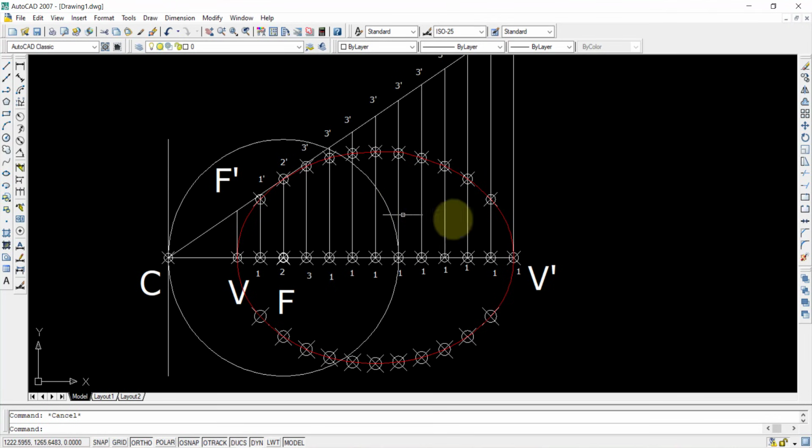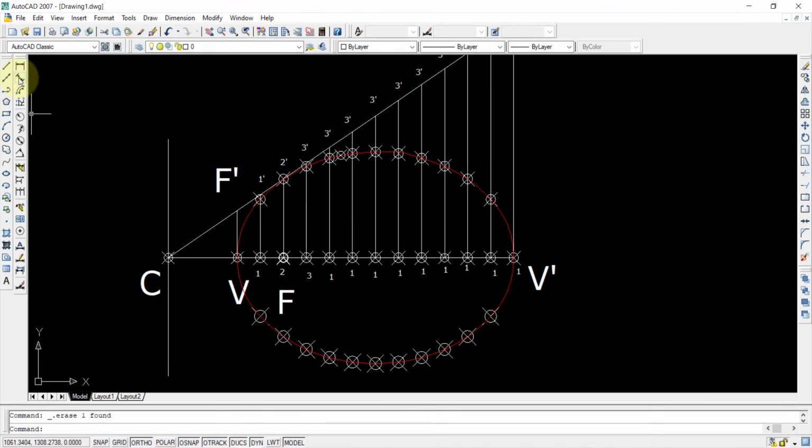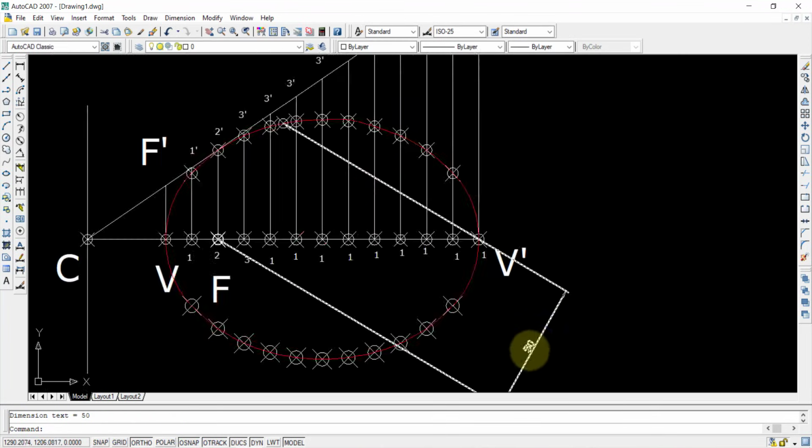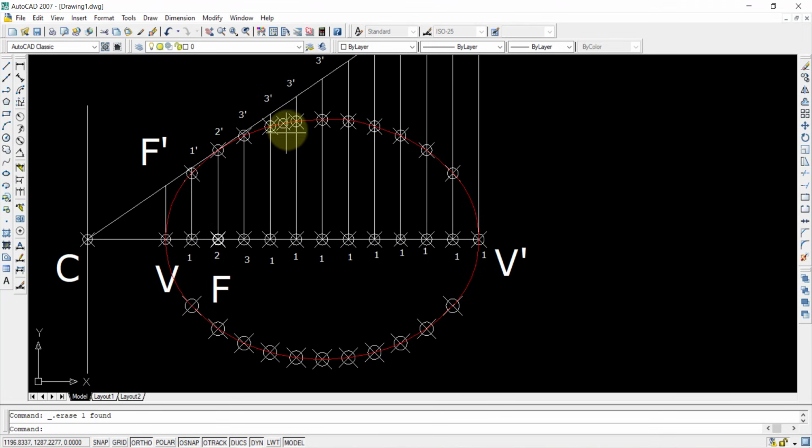Now we can see that I'm selecting the top figure. Here I'm selecting the intersection point. So this is my intersection point, which is 50 mm from the focus, you can see the dimension also here. I'm selecting the aligned dimension and drawing it here. How much is it? 50 mm, exactly 50 mm from the focus. So I'm selecting this as my point.